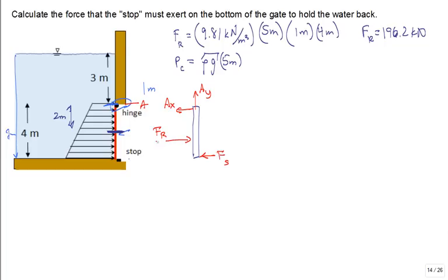Okay? So I then calculate y sub p. Oh, I forgot. Center of pressure. That's right. That's what the name is. It's going to be measured from the centroid of the area and increasing depth by I sub xx c, the centroidal area moment of inertia?